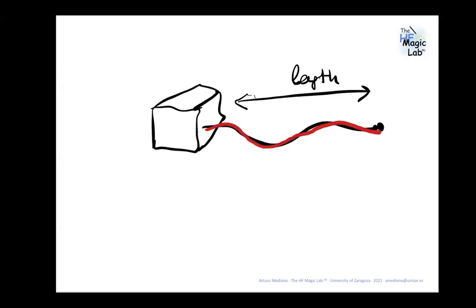The second idea: the cable is something that is passive. So if you are radiating, it's because you are exciting it with noise. So the second important idea is to kill the source. For example, if this is a ringing, you kill the ringing and you will not be able to excite this cable, independently of the energy of the frequency or the length of the cable. And another solution is if you introduce some kind of filter for this signal: ferrites, capacitors, inductors, depending on the application and the frequency.